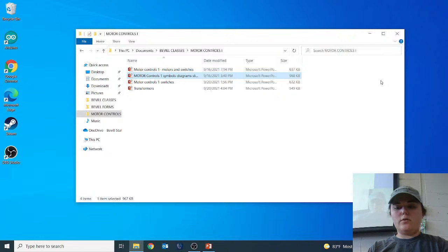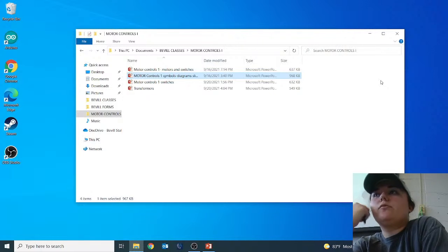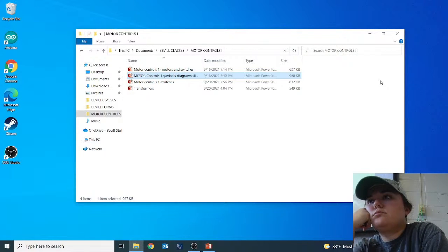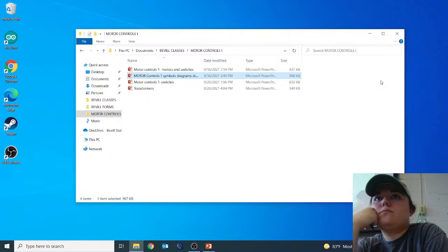All right, so we need to touch on a little bit about troubleshooting. What would you describe troubleshooting as, Caden? Basically, you use troubleshooting to figure out what's wrong with your system to make it work again. If it was an overload trip, you would know there was something wrong, so you'd have to trace it back and see what made that relay trip, right?